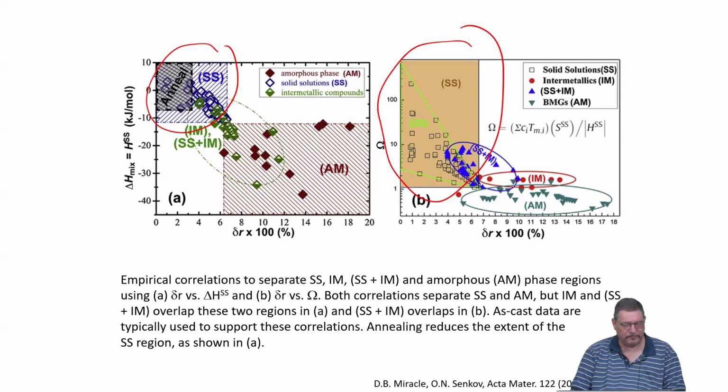And there in the literature we have very similar concepts which have been introduced many decades ago, and they have been reformulated not so long time ago by Professor Inoue from Japan, but it's basically still going back to old rules by Turnbull, who did this in the 1950s and predicted there in the 60s, which ratios of properties would favor metallic glass formation, because at that time it was still not yet confirmed that you can make metallic glasses.